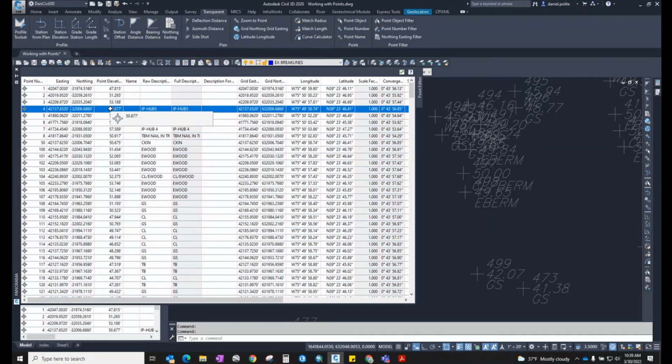But the one beauty about this, if you make a note, and it's happened to me plenty of times during surveys, where the rod person had adjusted the height from 6 foot to 7 foot and forgot to tell the person on the data collector that they adjusted that. Hopefully they took a mental note of where that's at, and then that way you can adjust those elevations. Basically it's a foot off, so you can add a foot to those elevations just by doing that change on the fly. Whereas with SurvCE, it was a task to get that done.